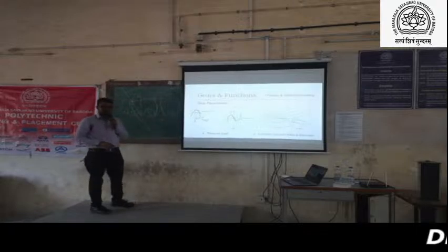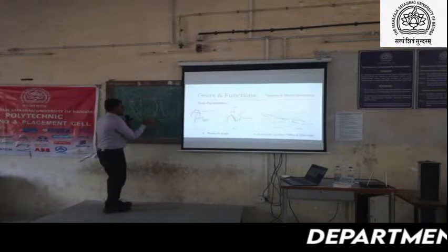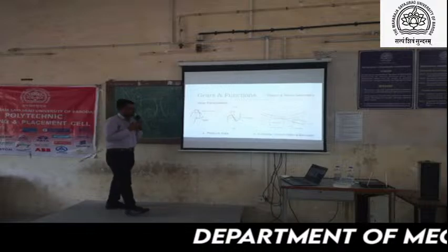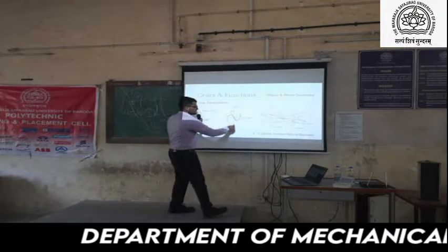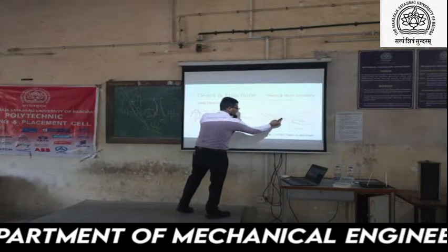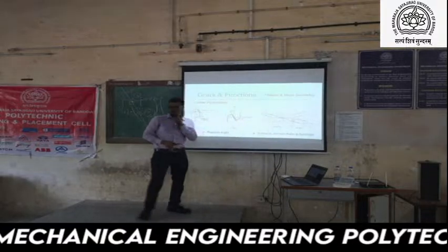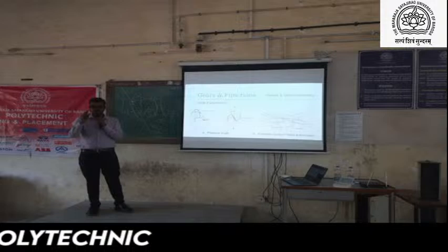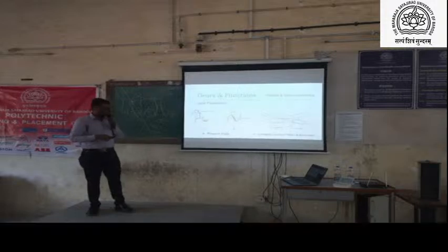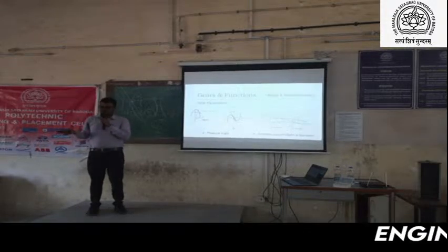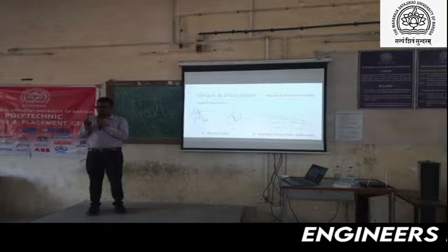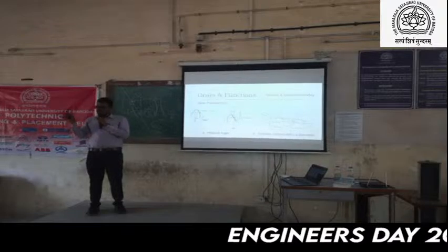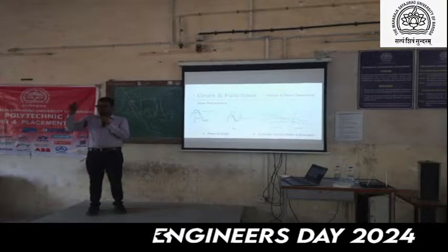Yes, no? This full tooth is also not fully getting contacted. Why? Because of the active contact length. So just 60% is getting contact in a single tooth. Then what about the other two? Just 40%, partially getting contact and partially getting removed. So 40 plus 40.